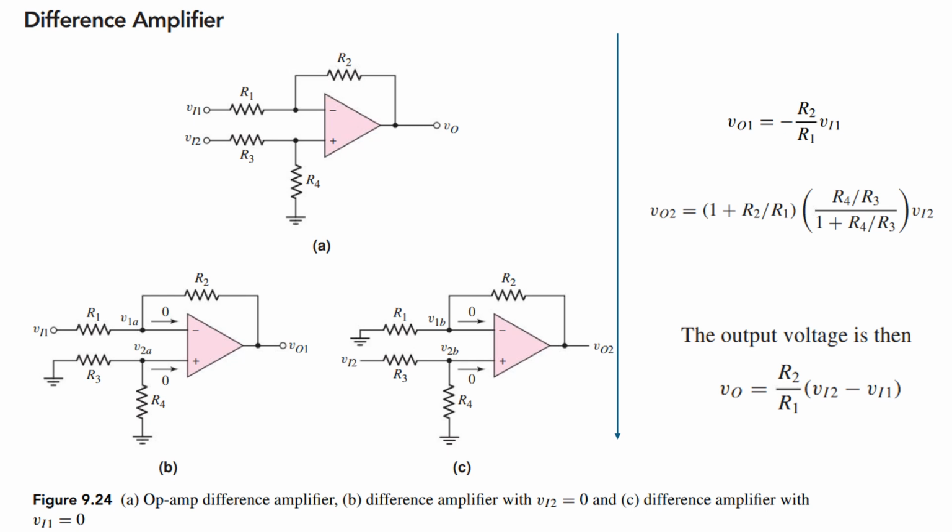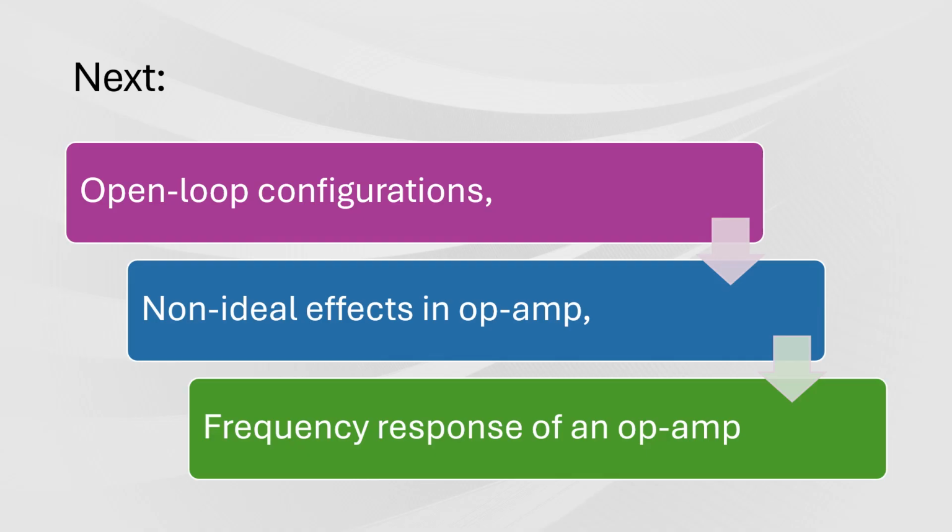And so find out the voltage at the plus, and that will be the same voltage at the minus terminal. And then if you know the voltage, find out the current between the two points, and then make it equal and get the value of the output voltage. So this is a simple way to find it out.